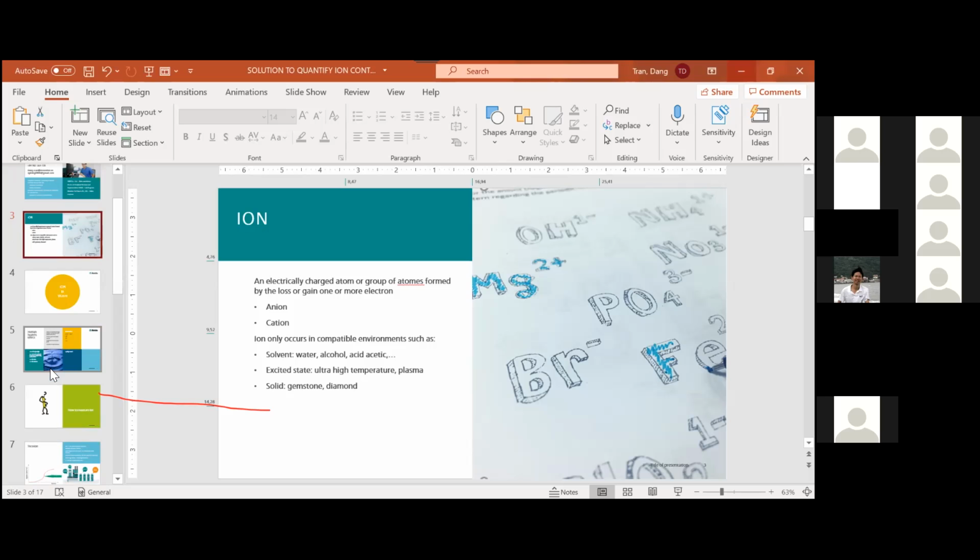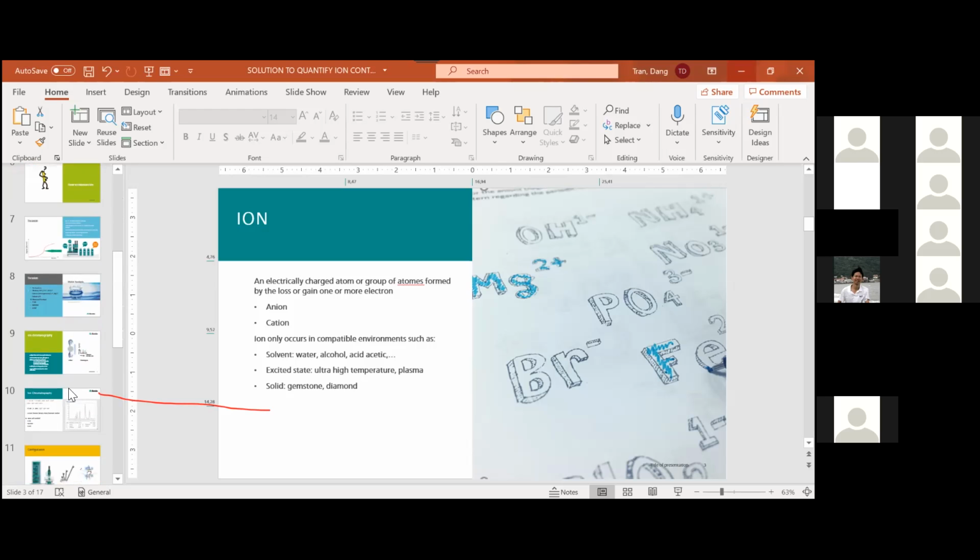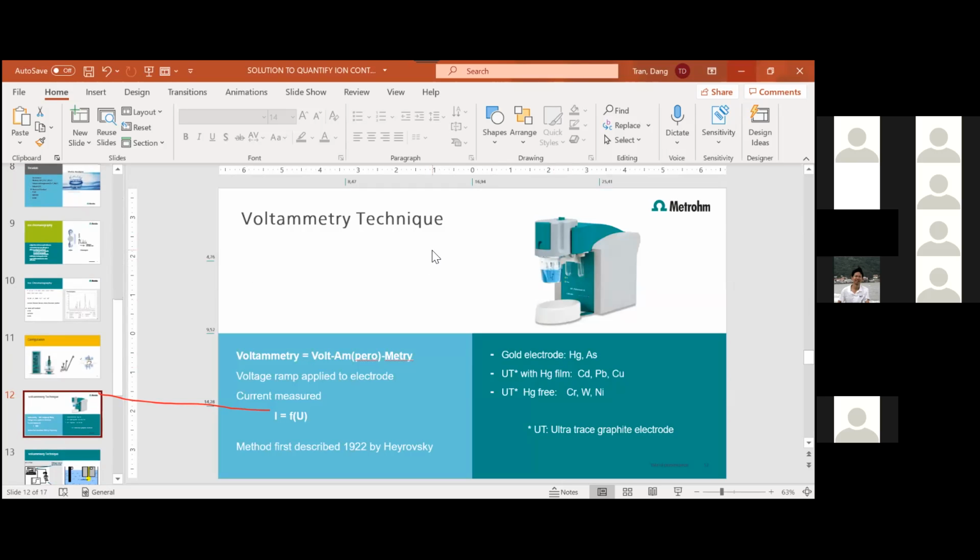Samsung Vietnam in the north uses titration to monitor the plating bath, and other similar voltammetry instruments to measure the ingredients in the plating bath, for example the brightener and the suppressor, from Atotech. These are ingredients that make the plating process smoother and more effective.